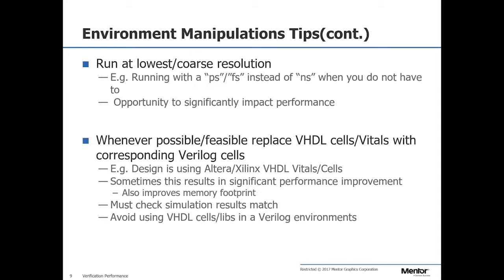If you ever do gate level simulation, use Verilog gate level representation versus VHDL VITAL representation. And that is a recommendation across all simulation tools, whether it's Mentor, Cadence, Synopsys, whatever. The VITAL gate level cells were never optimized for performance.